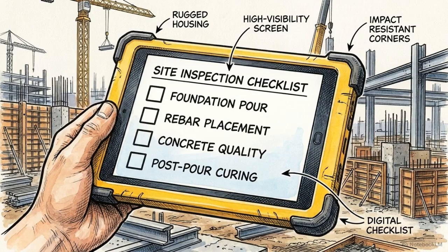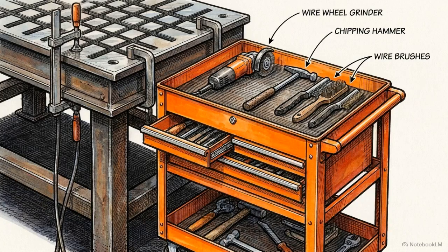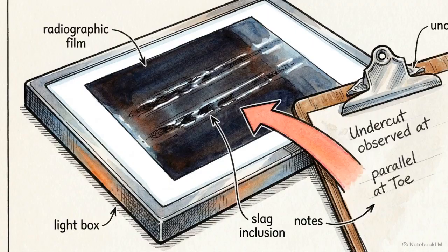For QA/QC professionals on site, this workflow translates into a specific 4-point site evaluation checklist. First, verify the operator's amperage and travel speed against the welding procedure specification to ensure the molten pool has the proper fluidity for slag separation. Second, confirm that inter-pass mechanical cleaning tools are present, material appropriate, and being actively utilized by the operators. Third, execute the 100% visual inspection post-cooling using the physical gauge toolkit to measure bead profiles against the limits of AWS Table 8.1. Finally, cross-reference those visual findings with the NDT reports, using radiographic or ultrasonic testing to correlate surface profile indicators with internal linear discontinuities.